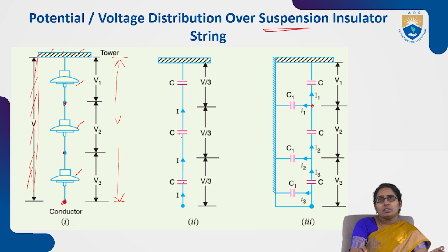So that capacitor is called the shunt capacitance, which is denoted with C1. Now for the first unit, the top unit, this is C1 shown like this, and the current flowing through the different parts. First, in the top unit, in the series path, the current is capital I1. Then the current flowing in the shunt path through the C1 is, let us say, small i1. For the top unit, the shunt capacitance current is small i1.